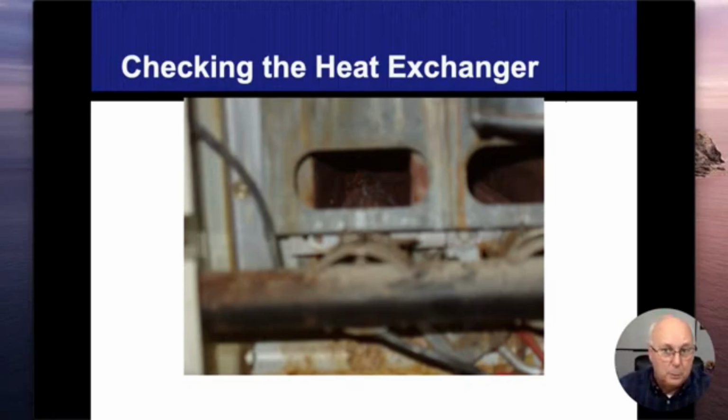Part of these pressure differentials, all right, I want you to remember, if you think that using a carbon monoxide detector in the circulation air is going to tell you if there's a crack or a hole in the heat exchanger, I'm going to try and convince you that it won't. Okay, I mean, if it's really bad, then it will. If it's so bad that we're getting carbon monoxide making it into the house, then hopefully you'll be picking it up that way. But small openings, small cracks, which are still dangerous, they're not going to bleed over into the circulation there because of those pressure differentials. All right, but it's still a dangerous seal.